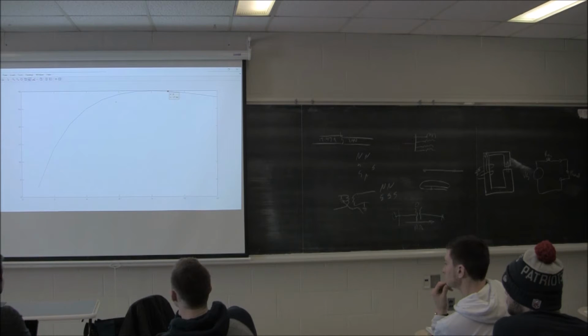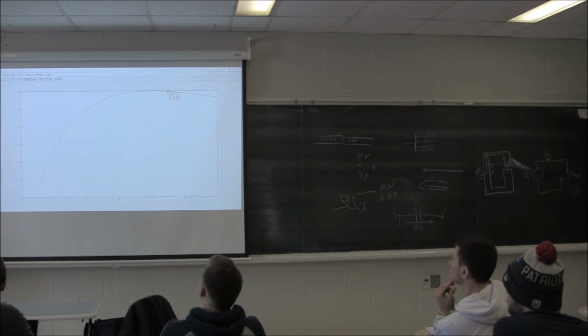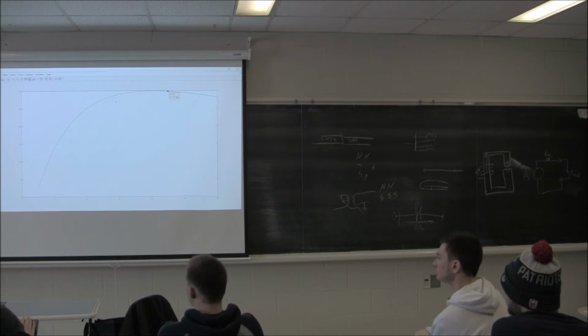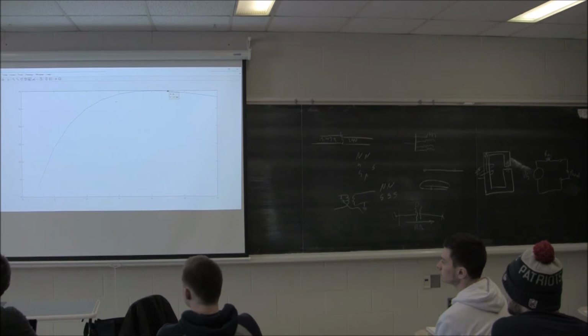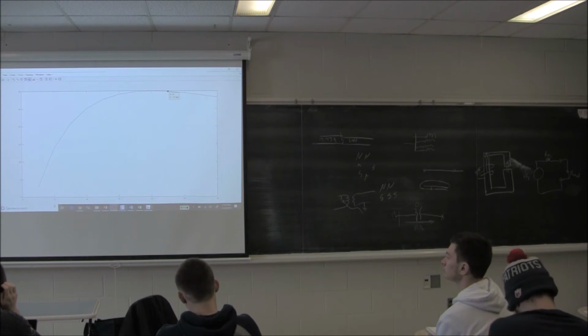So this is just a brute force way to prove max power transfer, which says your source impedance and your load impedance have to be the same, or your Thevenin equivalent impedance, right? So that's why we can have a really complicated source, but that is your R Thevenin, or what we'll learn in this class, you also have Z Thevenin, which is your Thevenin equivalent impedance magnitude. We'll talk more about that. Okay, any questions on our MATLAB script?